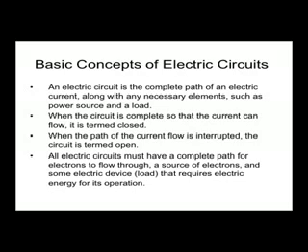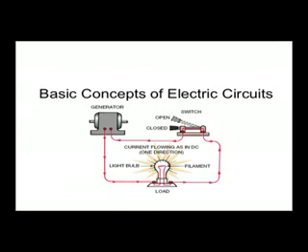There's a few examples of Ohm's law I'd like to go through. What is the current in the circuit shown below? This is a series circuit. One load, one path. E is 120 volts. R is 20 ohms. So E divided by R is 120 divided by 20, which is 6. So the current is 6 amps.